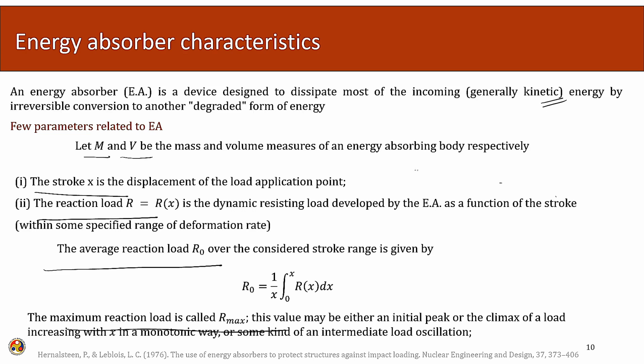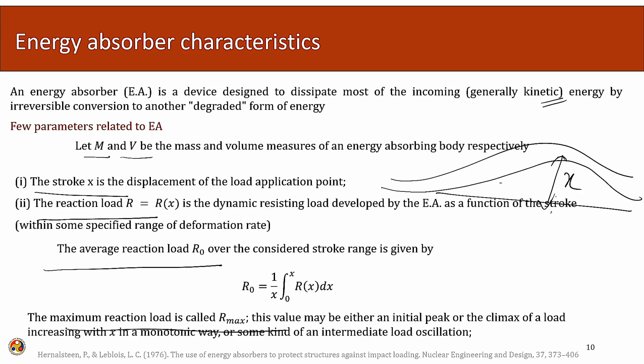The stroke, as you remember, we defined as the displacement of the energy absorber at the load application point. The reaction load is the dynamic resisting load developed by the energy absorber, and it is given as a function of the stroke. Average reaction load we defined as an integrated area of the reaction stroke curve, and it is averaged out over the entire stroke length.